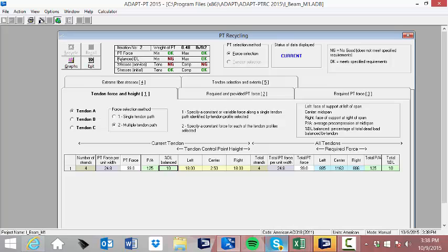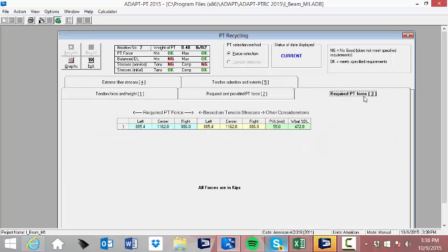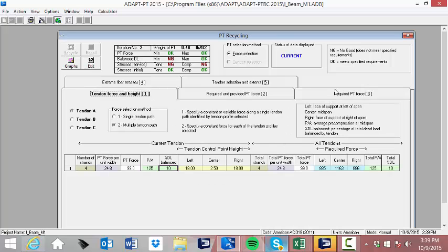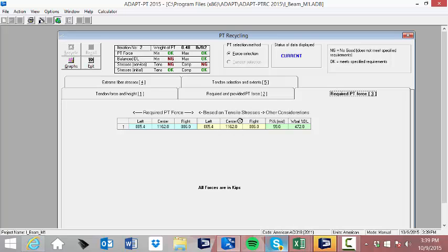And if it can't meet balance loading or stress conditions, it would then come back and report back, no good in this case for the balance loading and also for the stresses. And we can see the force right here, 99 kips, is actually required for P over A. So the program couldn't find an acceptable solution to meet all three, and it reports back only the force required for P over A. If we look at the required force for stress allowance, it's 1163 kips.